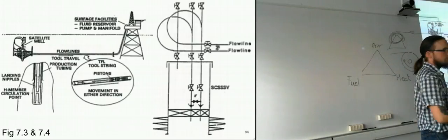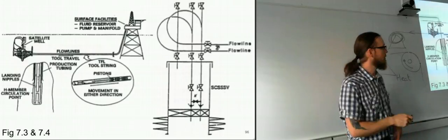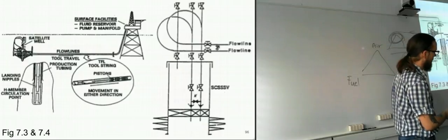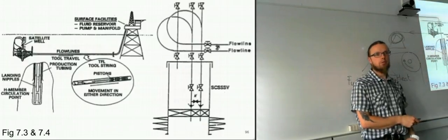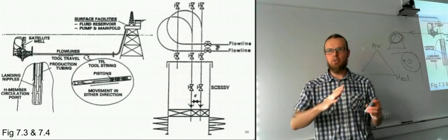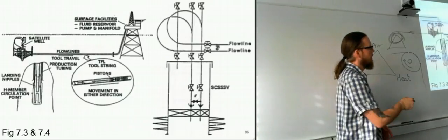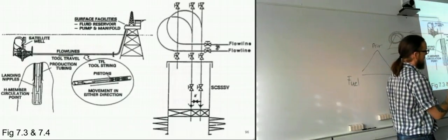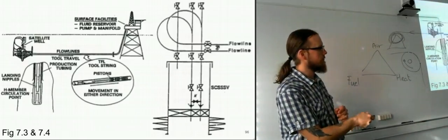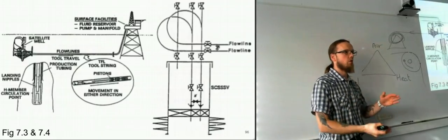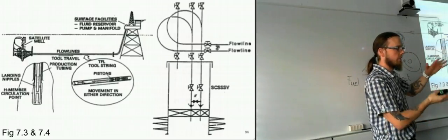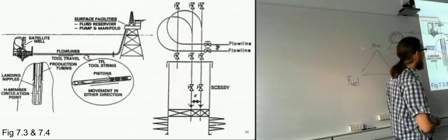And then it's a matter of adjusting the pressure inside the flow line in order to get it to stop at the correct spot, because you have pressure coming up from the reservoir, and then when you are counteracting that, you are pumping up more or less the same pressure, but then you are pumping it to a certain point so that it will be pushed down here. But then when it gets to roughly the correct location, the pressure from the reservoir will sort of equalize with the pressure from the other side of the tool, so that it will just stop there. So it will just stay there.